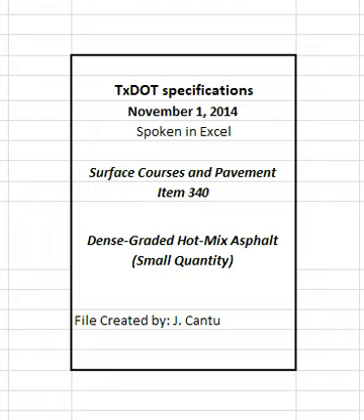Do not intermingle contractor-owned RAP stockpiles with department-owned RAP stockpiles. Remove unused contractor-owned RAP material from the project site upon completion of the project. Return unused department-owned RAP to the designated stockpile location.